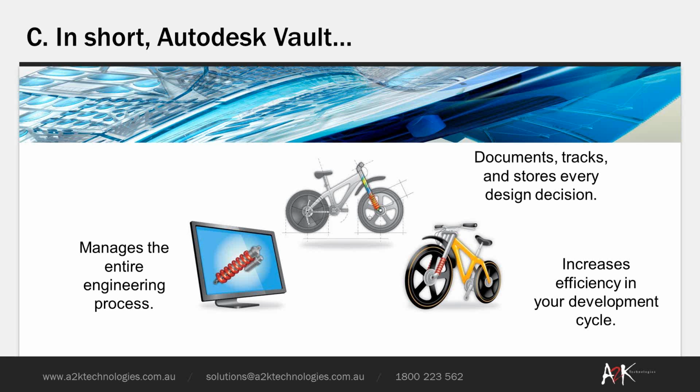And it also allows you massive increases in efficiency, because you can use Vault to change names on 50 parts in one hit. You can use automatic file naming. You can use rename and copy designs to allow you to reuse existing designs and maintain all the links. So there's massive benefits, and most of those things that I mentioned I've gone over in part one of this webinar series.